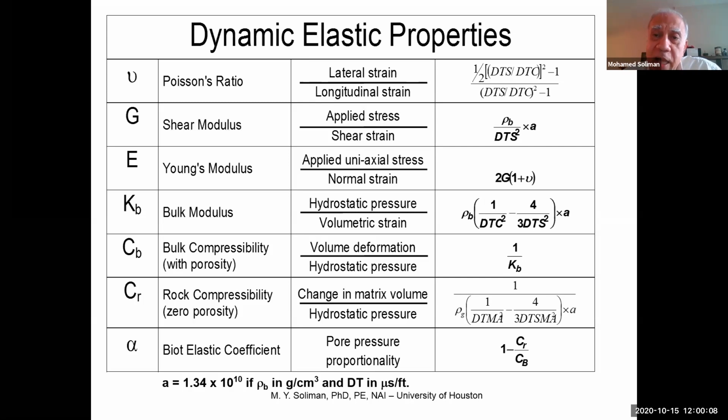Well, probably not. There are two different types of measurements, one static and one dynamic, and they will be different. Which one is larger depends on a lot of parameters, so we're not going to get into that. But which one would you use? Most people are going to say dynamic, and the answer is no. Use static values in designing the fracture.